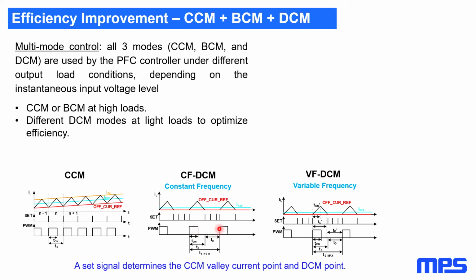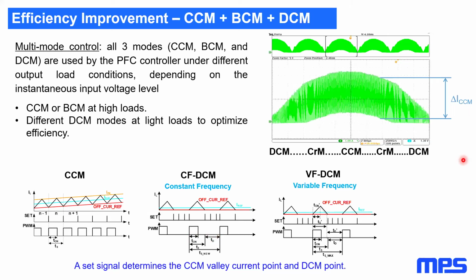So it means there's a more complex algorithm, because we're not just letting the dead time be added automatically, but we control it while we add the dead time so that the on time also follows, to keep the power factor high.